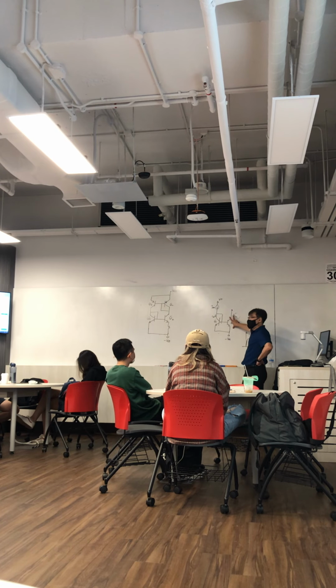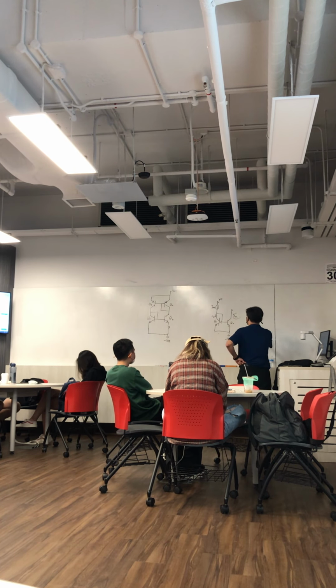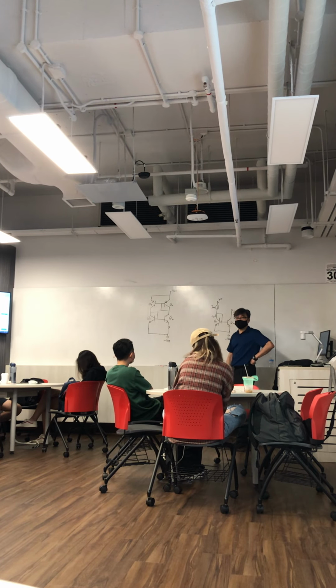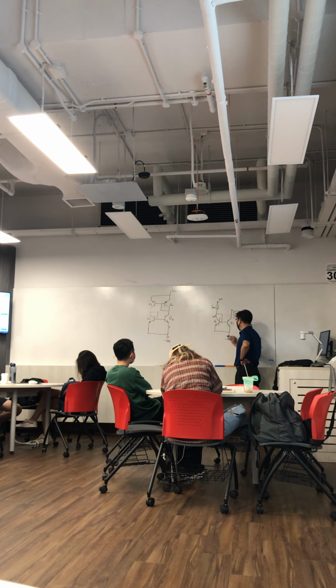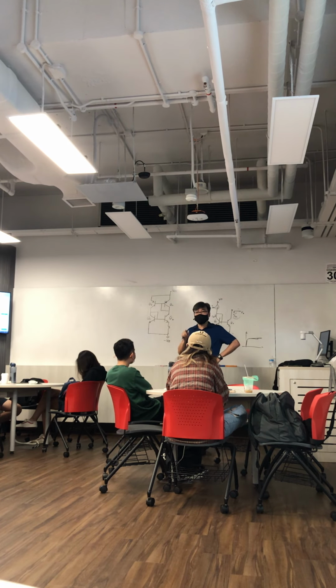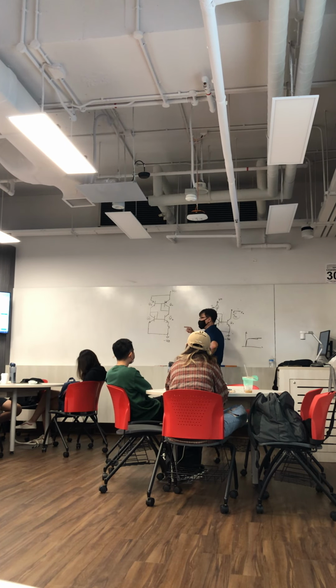This guy is the AC variation; any variation here over the current is the dynamic resistance, which is your RO. If you look at the voltage here, RO, AC resistance. So if you look into here, from here to here, you change this guy to ground, AC resistance. You see here to here is just RO. I just want to show you to make it easy for you. You notice this guy is a diode. So if it's a diode, then later I will show you for the MOSFET. This is more or less close to 1 over gm,